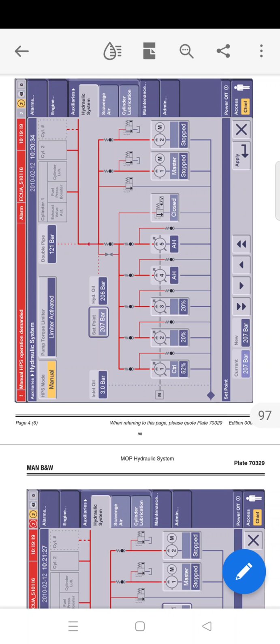Adjustment of the oil pressure set point can be done from the set point display, but the actual set point is always shown. The engine must be running. The actual oil pressure is shown at the display as hydraulic oil. Adjustment of the set point, that is the chip level and manual mode, is only intended as an option in test or failure situation. As default, the normal operating pressure is in the 200 to 300 bar range and is set at commissioning. The engine shutdown level is approximately 140 to 180 bars.